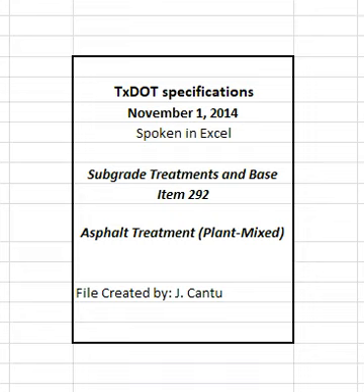4.4 Placement operations. Prepare the surface by removing objectionable materials such as moisture, dirt, sand, leaves and other loose impediments before placing the mixture. Coordinate mixture delivery and paver speed to ensure a continuous placement operation. Suspend placement operations when, in the opinion of the engineer, a continuous paving operation is not maintained. Place the mixture to produce a smooth, finished surface with a uniform appearance and texture that meet typical section requirements. Offset longitudinal joints of successive courses of stabilized base by at least 6 inches. Place the mix adjacent to gutters and structures so that the pavement will drain properly.